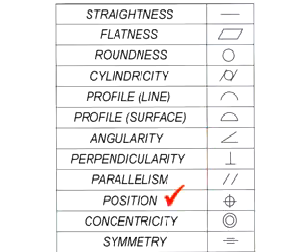Position could be position from, as an example, another hole, but it's often position from a reference point in X and Y. Concentricity, however, is in relation to an axis, and that could be a rotating axis or just the center of a cylindrical part. The last one on our short list here is symmetry, and a part can be symmetrical about a point, but as a general rule, symmetry is indicated as being equal side to side from a line, which is most often a center line.